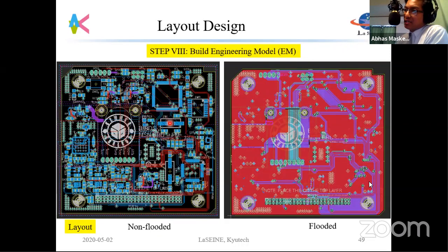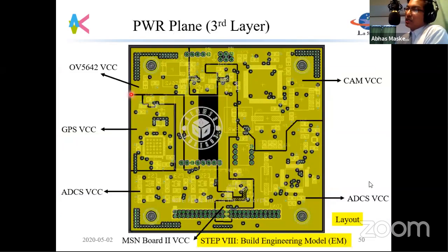You can see here that it's symmetrical. You have the load capacitors here, the oscillator, and the way the traces are going. These are very important things. You'll also notice that no traces are going underneath oscillators. So this is just to comply with EMI conditions, right? So you want to be careful how you design it. This was a 6-layer PCB.